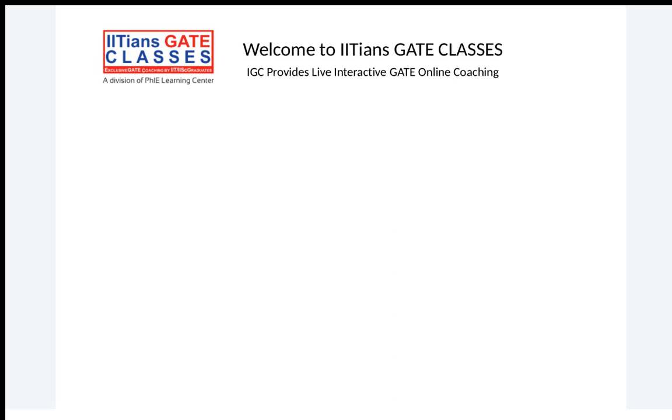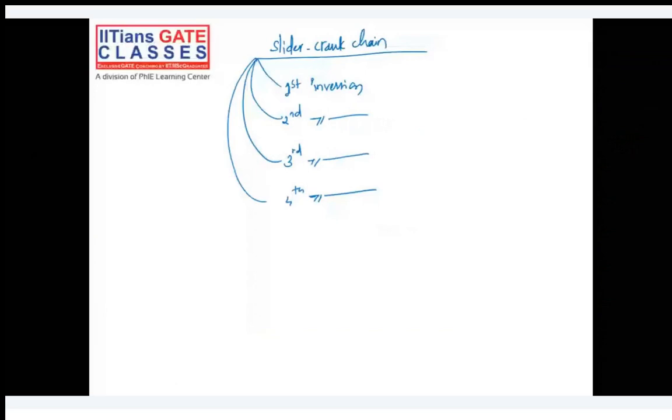Okay, so in the first inversion, basically the first link is fixed, and the rest of the links are as they are, and the examples of this are the reciprocating engine and the reciprocating compressor. Okay, the examples of this are reciprocating engine and compressor.